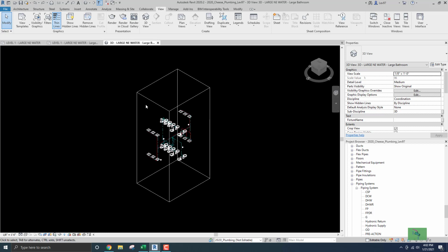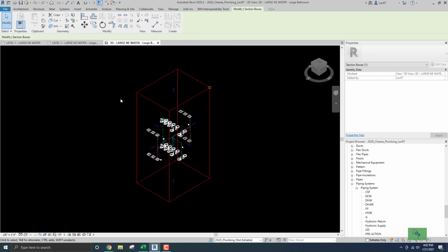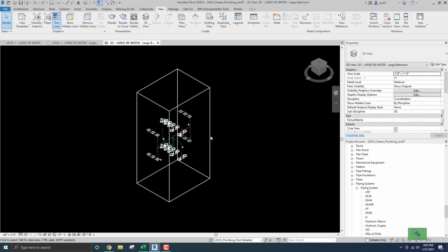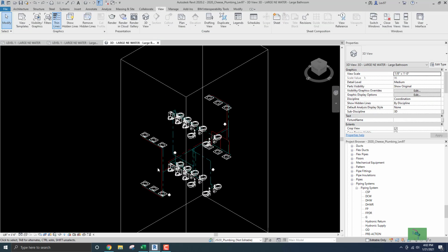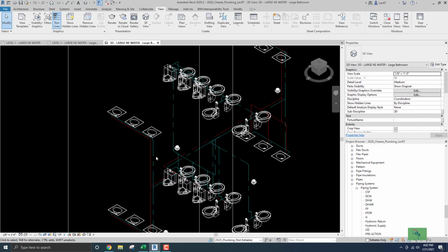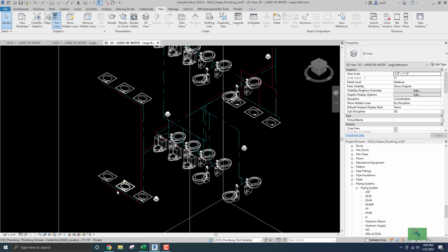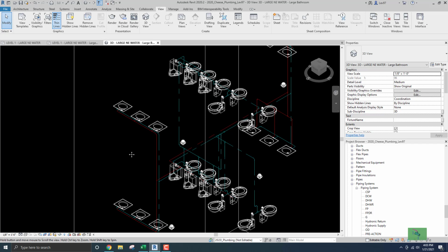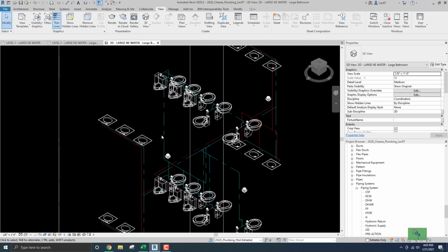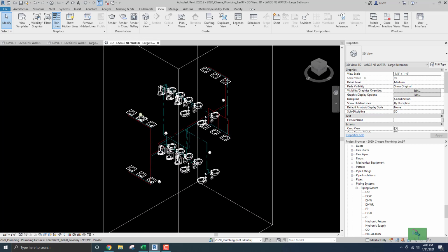So we got that, and what I'm gonna do now is I need to put this on the sheet, but you guys can figure out how to label these, right? So just let me do a little bit of that. So in order to do that, you have to save orientation and lock view, right? Save orientation, lock view, in order to label your 3D view or your riser view.